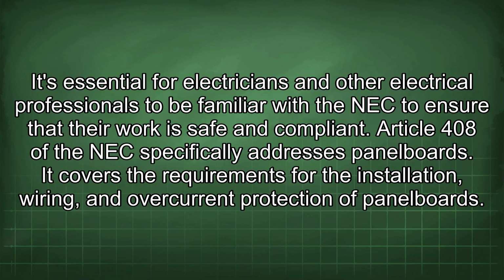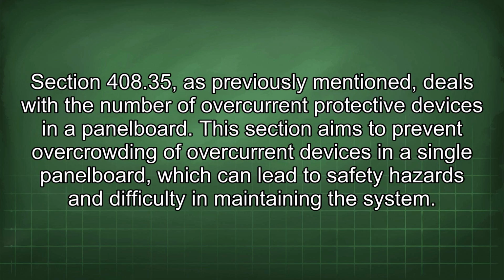It covers the requirements for the installation, wiring, and overcurrent protection of panel boards. Section 408.35, I previously mentioned, deals with the number of overcurrent protective devices in a panel board. This section aims to prevent overcrowding of overcurrent devices in a single panel board, which can lead to safety hazards and difficulty in maintaining the system.